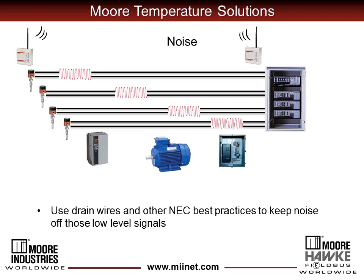When they are direct wired back to the control or data acquisition system, those extension wires serve as antenna for noise. If that noise gets into the signal, it doesn't take a lot of distortion to mess up a low-level millivolt signal.